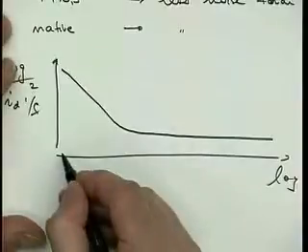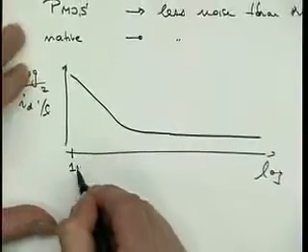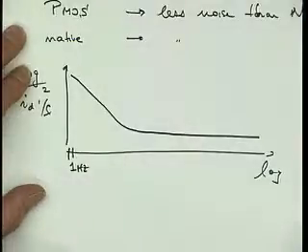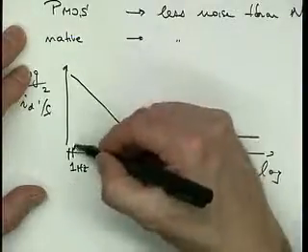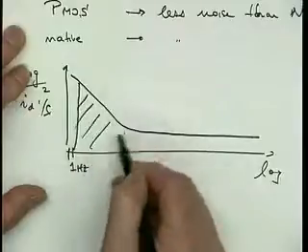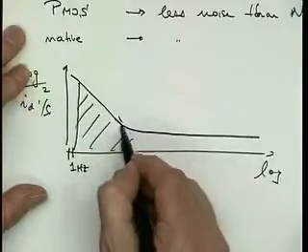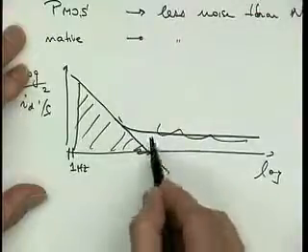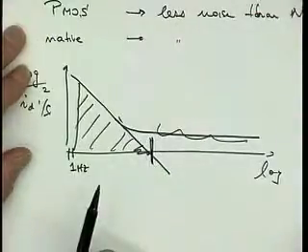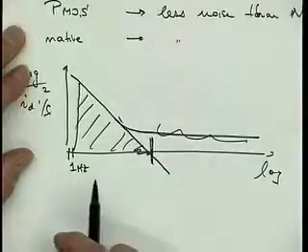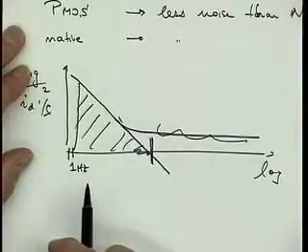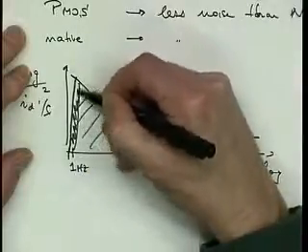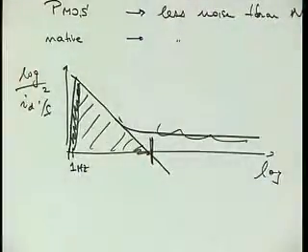Here is 1 hertz, and here is 1 year. All we did is we started with the 1 hertz case. We started with all of this noise. Well, actually, we didn't include any thermal noise. So we integrated up to here. Let's say this was 1 megahertz. And then when we switched from 1 hertz to 1 year, we added this sliver here. Well, big deal, right?